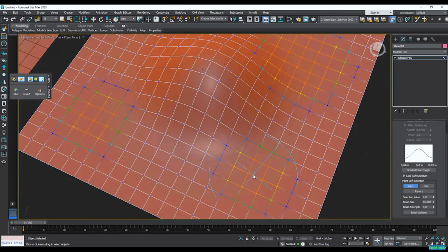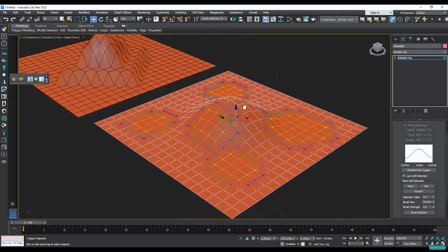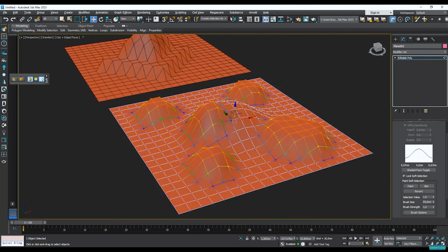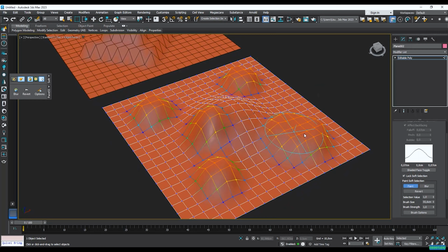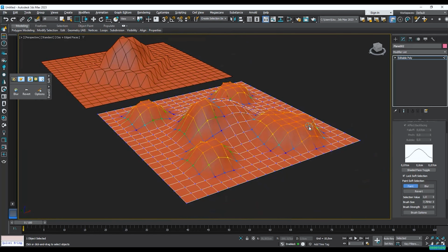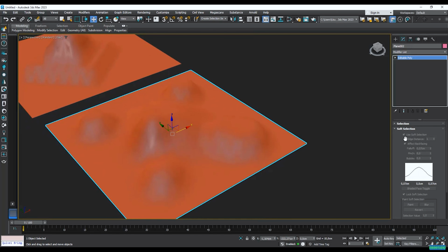And now I want to select these parts of the plane, and now let's hit the W for our gizmo, and that has the same effect. Now if I go ahead and paint it again, and let's say that I want this to turn into a harder selection, let's just reduce the value for this brush. I'll just paint on top of it, and you can see how it has changed into this orange color. So this is very useful when we're creating terrains.